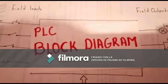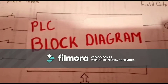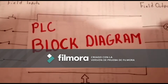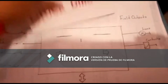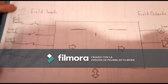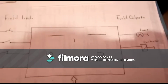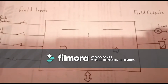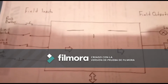Well, the PLC block diagram consists of 3 principal parts: input-output modules, a CPU, a central processing unit, and a programming monitor. As you can see here, this is our basic diagram. Here's a field of our inputs and everything that we could use. And on the other side, we have a field of outputs that consists of lamps, contactors, motors, and so on.